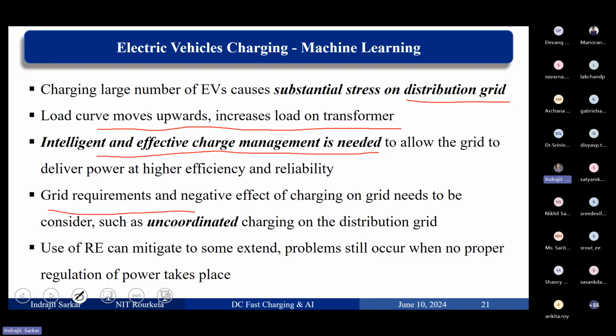If it is a weak grid, it is further going to affect it, because nowadays it is told that Indian Oil filling stations will be equipped with charging stations as well, EV charging facility as well. So if that is the case, fine, but you have to take care of the grid scenario at that location. If that grid is capable enough to cater that thing, it's fine. Otherwise, you have to check a suitable location where you can install it.